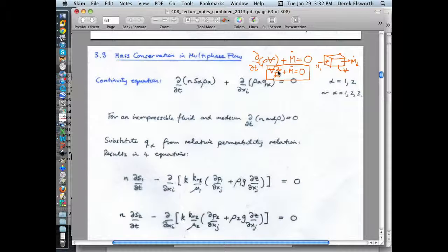And so you might have thought you'd never see that again, but this is kind of the basis of any groundwater flow problem. And it says that mass in minus mass flow out. So this is a volumetric flow rate or a velocity times a density. And so you can imagine that the velocity times the density over a particular cross-sectional area, A, gives you a mass flow rate. So it's this term here. And this is a term which relates to the density change for a constant volume.